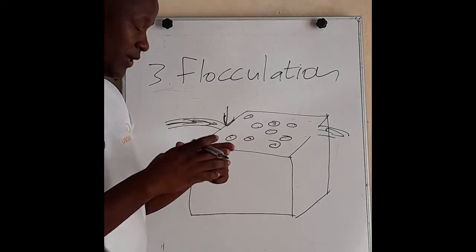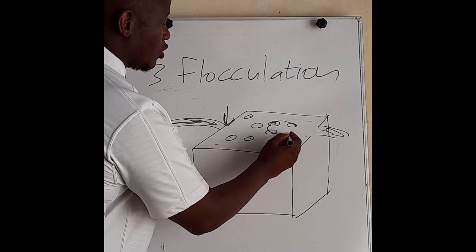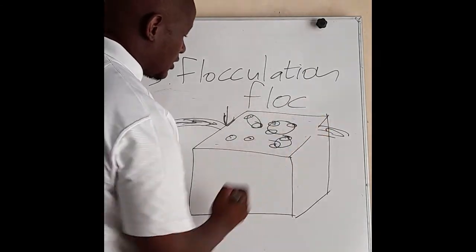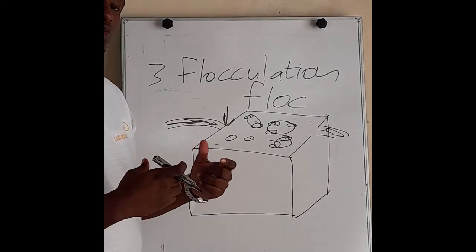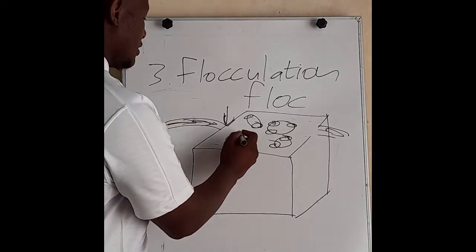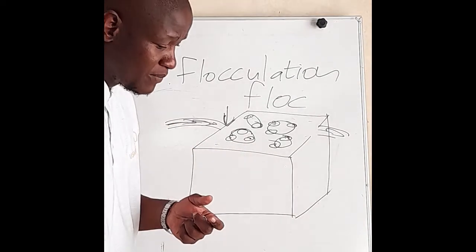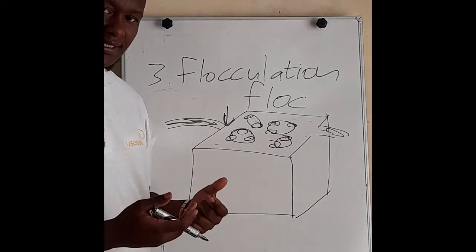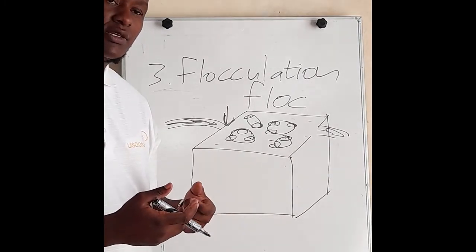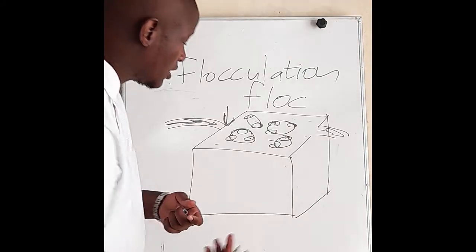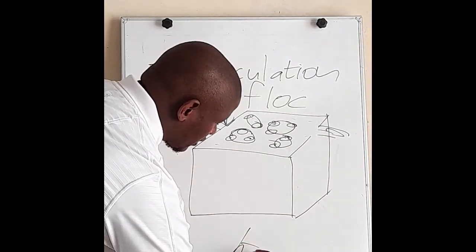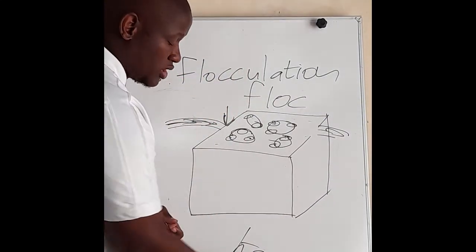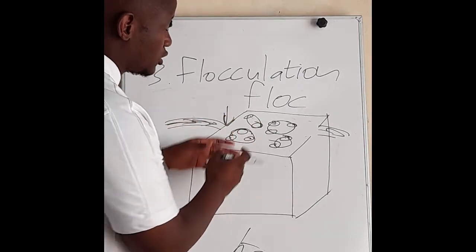They're going to coagulate together, and basically they're going to form what's called floc. Because of that chemical, they're able to adhere together, and then they form floc. By so doing, immediately something gets bigger in size. It changes the density. By changing the density, basically you're changing also the mass, because your density has a unit of kilograms per meter cubed. So you've changed the mass, you've also changed the volume of that particular solid.